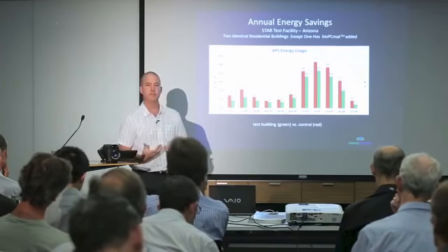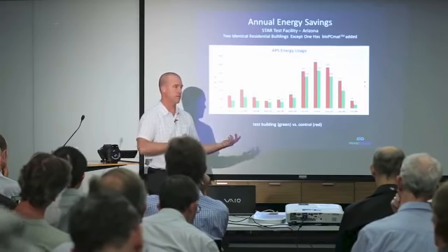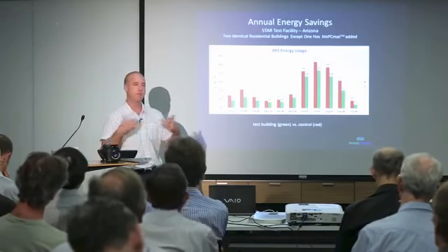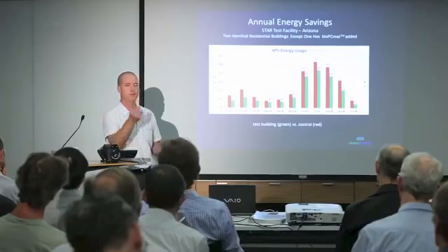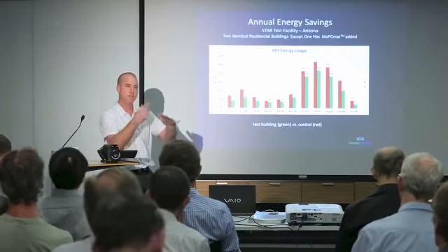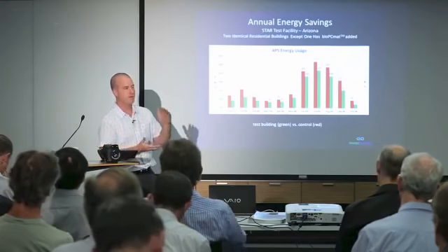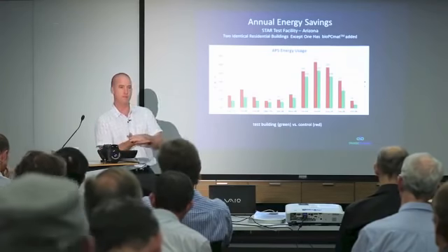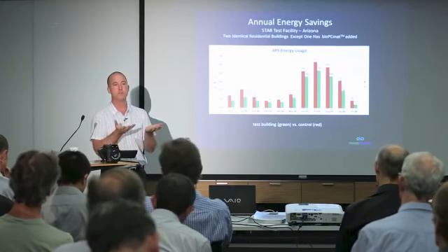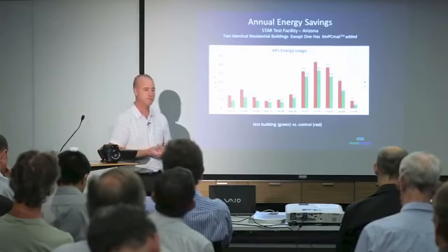It's the same if maybe I've got windows with a lot of sun hitting them. Same thing with the cooling side. If it's full of energy and you open the windows at night, on a house you get about 30 air changes per hour, typically. So you open the windows up, the air might be 18 degrees outside, it'll refreeze the material back to 18, 19 by the time it gets to morning, because there's enough air changes to do that. And by then your ceiling is frozen again, like the sample you've got in your hands. Then you close the curtains and the windows, and the house stays really cool because it's absorbing all the heat, keeping you cool.